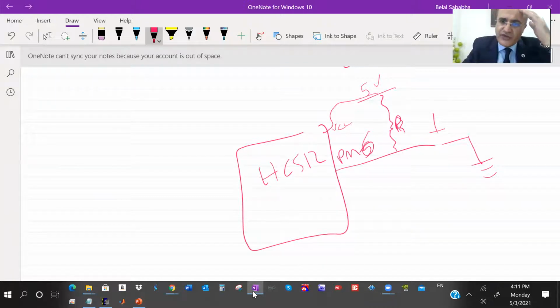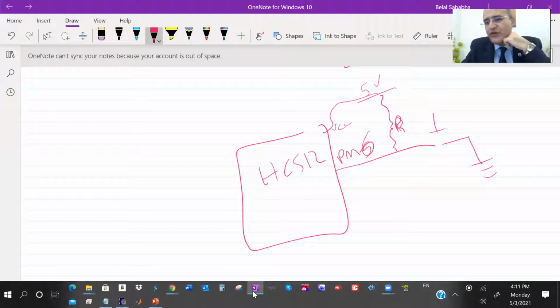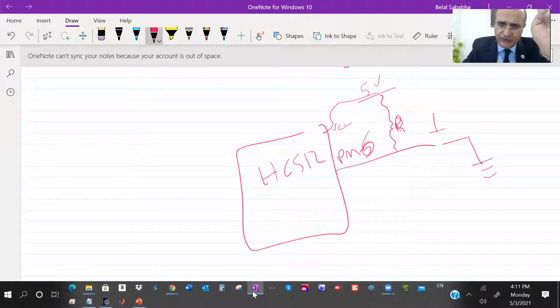So this pin is always high. When I push the button, it will go to low. What we're going to do in this demo, we're going to do it in 2 ways. First, we want to press the button and read it as a poll without an interrupt. Then I want to go to port E1, which is pin number 55, which is also the IRQ pin.